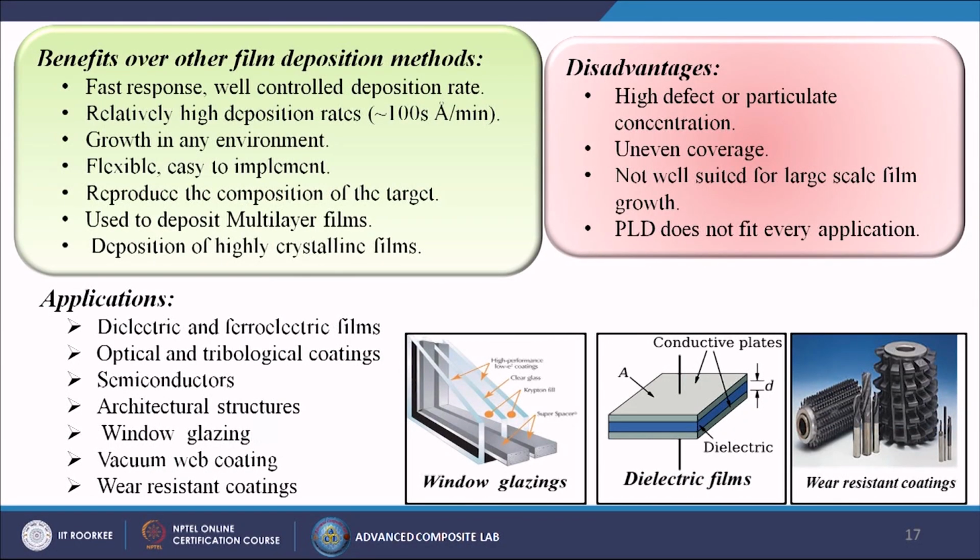Then there are certain disadvantages also: high defect or particulate concentrations, uneven coverage, not well suited for large scale film growth. PLD does not fit every application. So, what are the applications? Dielectric and ferroelectric films we can make, optical and tribological coatings we can do, and we can use it for semiconductors, architectural structures, window glazing, vacuum wave coating, wear resistance coating.